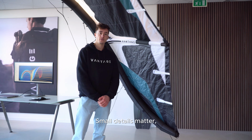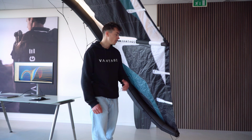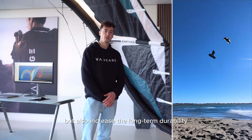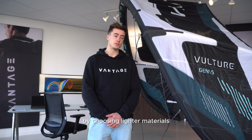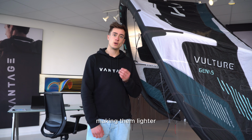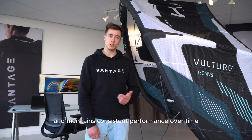Small details matter, so that's why we implemented patterns at the trailing edge to reduce flutter. Flutter is a fast vibration of the canopy trailing edge. By reducing this, we reduce the drag, but also increase the long-term durability of the trailing edge. For the material, we didn't sacrifice on strength and durability by choosing lighter materials. Instead, we optimized for structure of the kite, making the kites lighter while keeping the durability of the materials high. This made sure the kite lasts longer and will perform consistently over time.